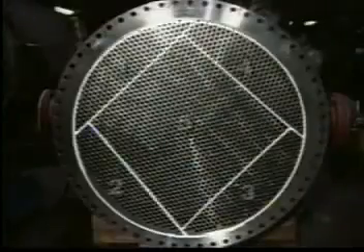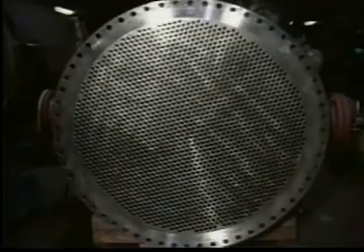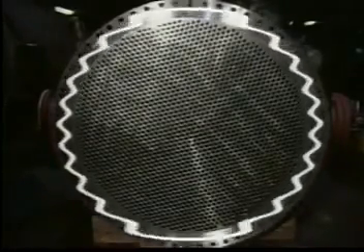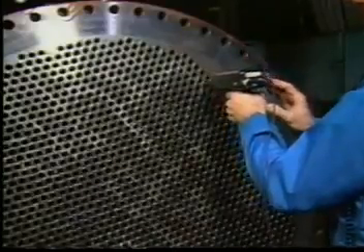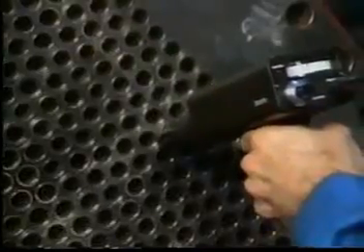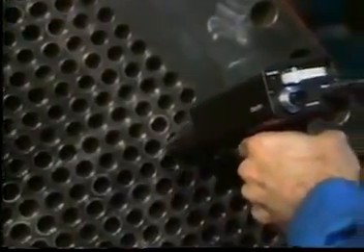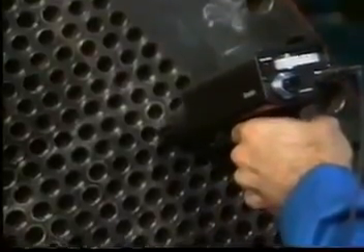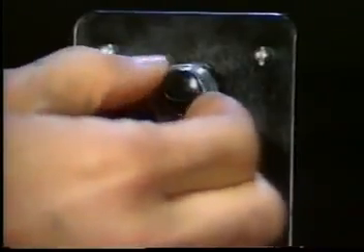In peripheral areas, create zones for comparison testing of tubes with similar intensity readings and sound quality. Since tone generators are on top of peripheral tubes, they will be vibrated during testing of areas near the generators. For an accurate test, test one zone at a time. Reduce the ultraprobe sensitivity to read about 50 on the meter and scan for variances between tubes. Another variation may be to retain maximum sensitivity and reduce the warble tone generator's amplitude while scanning for these differences.